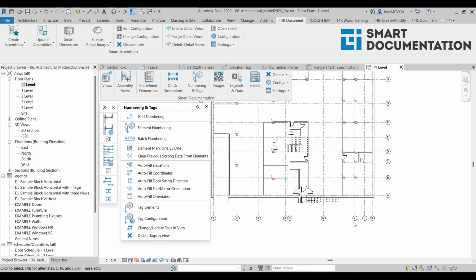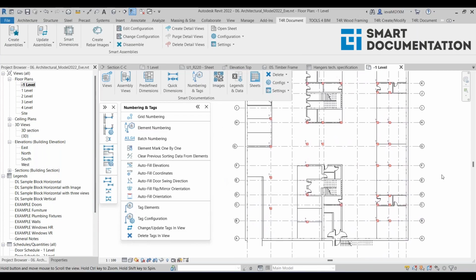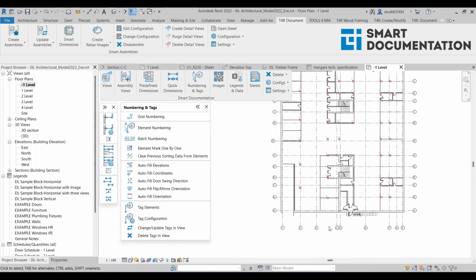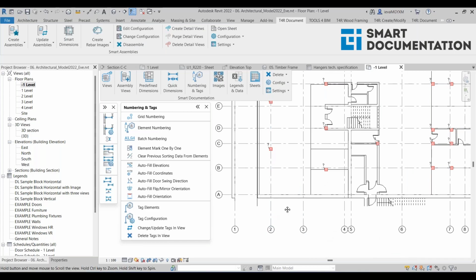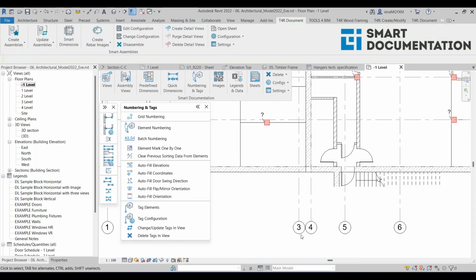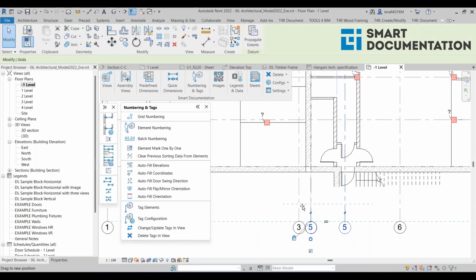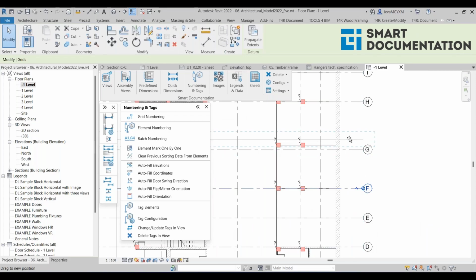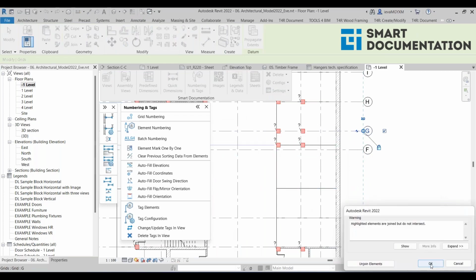And now what's also nice is that when I added that tick mark, that means I will no longer have to renumber them because they will be renumbered automatically. So for example, now I will move this third grid right here, and you can see that the numbers changed automatically. So now it's tracking the placement of the grids.